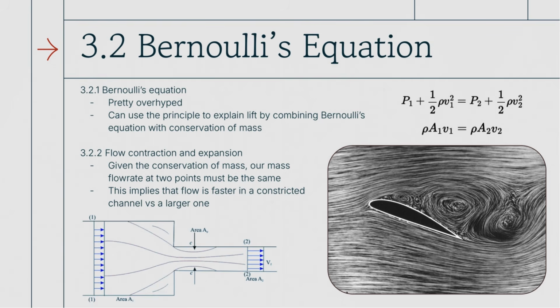It's got to move the same amount of mass through a smaller volume. And so what happens is the flow has to accelerate. It has to go faster. So kind of the same thing here at the bottom. You have a much larger area. The flow is moving slowly. And then if that same amount of fluid has to move through a smaller area, it has to accelerate. Pretty intuitive, but it's the same thing here.